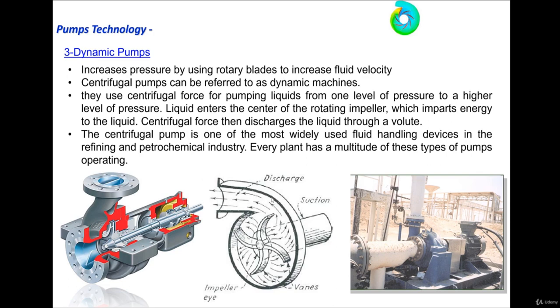This pump is called an overhung pump. This is the suction, this is the discharge, and the pump rotor is supported by bearings, one, two, three bearings. And for sure, behind the impeller there is a certain amount of sealing or controlling of the fluid emissions. So this is a mechanical seal or packing.